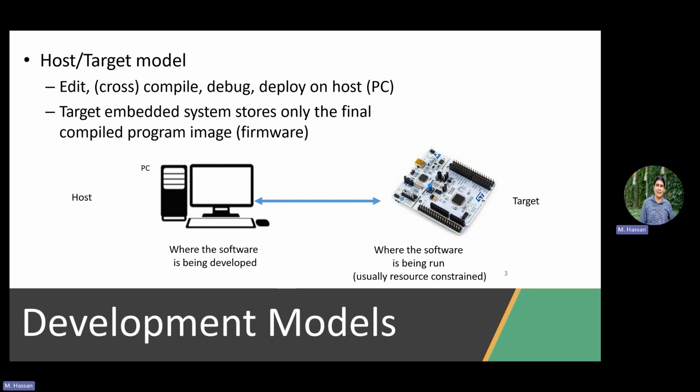For the target machine. It asks you what your target machine is, and they do a process called cross compilation. In the background, there is a very complex process that the compiler is doing for you through the IDE. It says, right now I'm going to execute and simulate this code on an x86 machine. But at the end, when I create the hex file, the assembly, and the binary, I'm going to create it for an ARM machine, for example. This is called cross compilation. Without cross compilation, we couldn't do any of this, because you cannot write software on a machine and target a different machine unless it's the same ISA. Good.